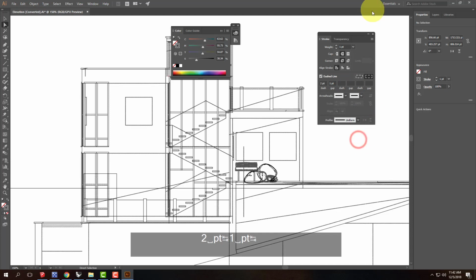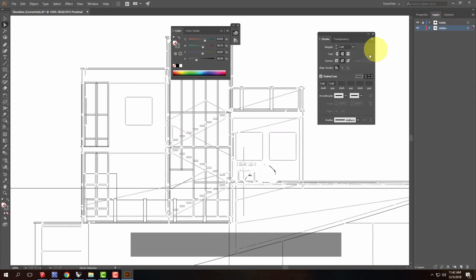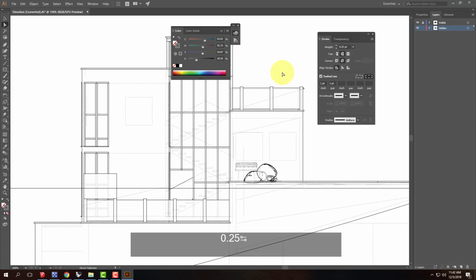And then when I click off, you guys will be able to see that I have lots of hidden lines. Doesn't quite look right. They're a little bit too thick. I'll select all of them again, and I'll go into my weight here, and we'll make them 0.25 so they're nice and thin. And suddenly they look a lot better, except you guys can't see them.